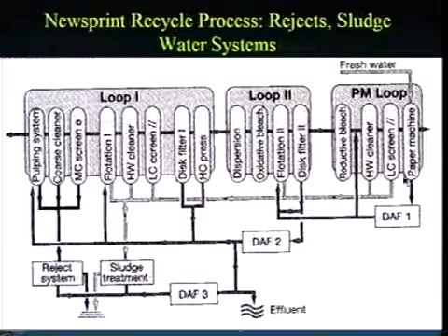Well, all right, so the water here actually is relatively clean, and it's going to go to a dissolved air flotation clarifier. That dissolved air flotation clarifier can work in 2 ways. In one sense, a lot of the times these DAFs that are on a paper machine are used as a save-all. And so the solids that we get here, actually they're pretty clean and we can put them back into the product. So we do that. And then the other thing is we reuse the water. So some of that water goes here.